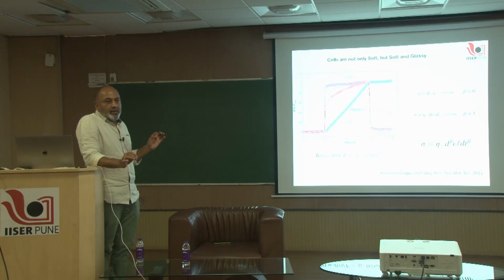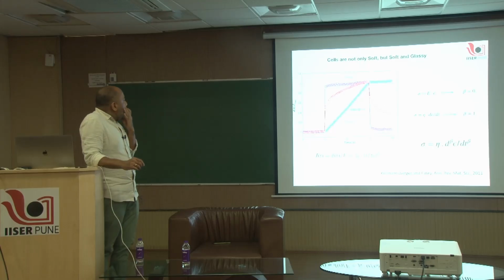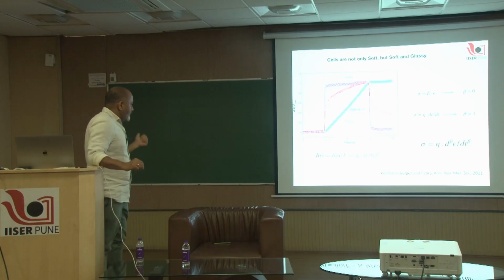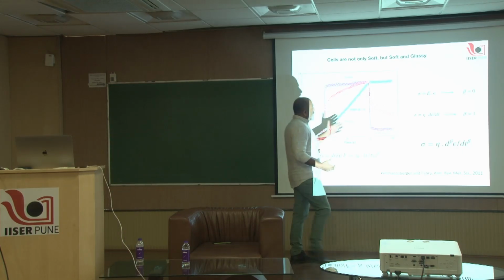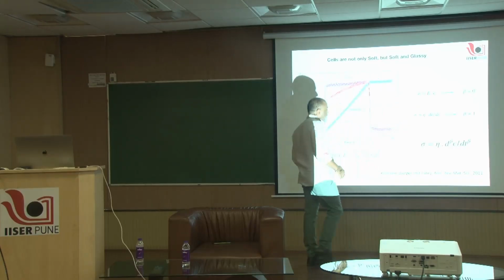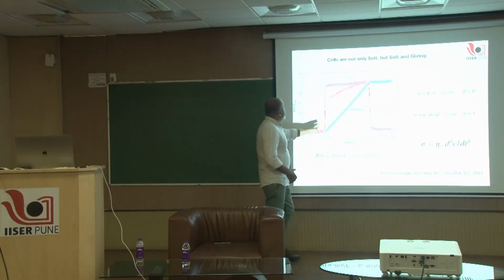Characteristic creep relaxation, you can say, because that part is a creep in a way. So what can one do? One can come up with a constitutive equation just like this to describe this particular rise.